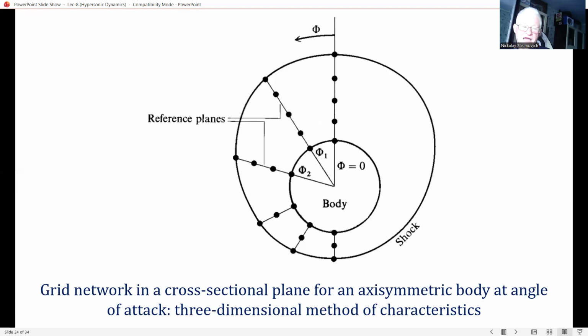Also, a detailed presentation of the three-dimensional method of characteristics is beyond the scope of our lecture, because it's a real scientific and research task for today. It is important to know some results obtained with this method. In particular, we will examine the calculations of Rakich, who utilized a modification to the general philosophy of the three-dimensional method of characteristics, which somewhat simplifies the calculation.